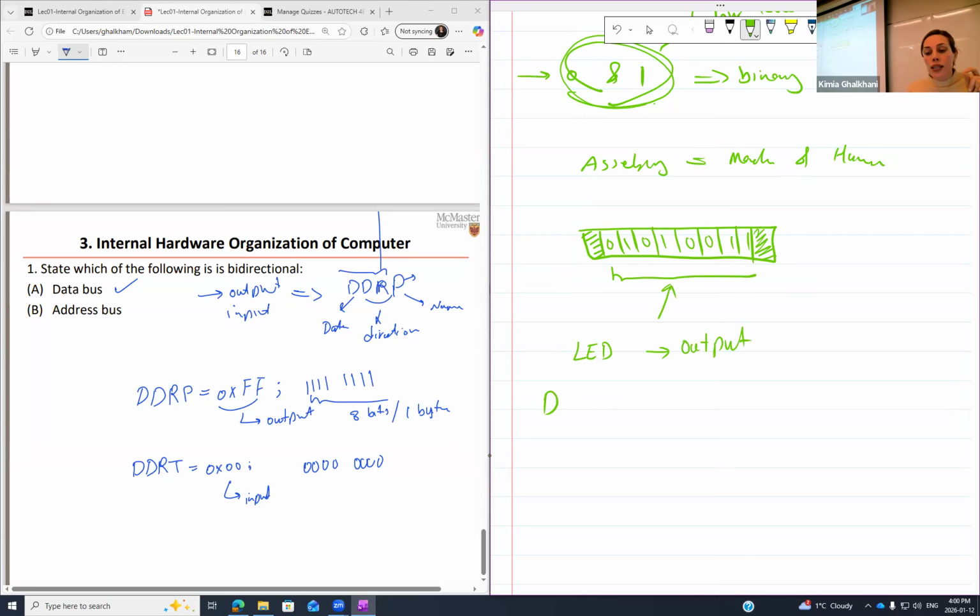First, I give it data. The setup in the lab is connected to port H. So I have to say DDRH 0xFF. Means LED is just output. Output means just turn the entire register to become output. Then later I can mask them. I can say PTH, means port H, and then I can just mask it, either through hex command or through whatever other methods I have for bitwising.